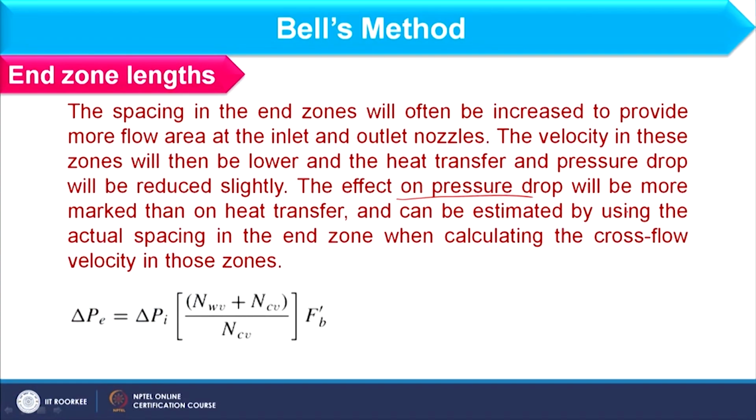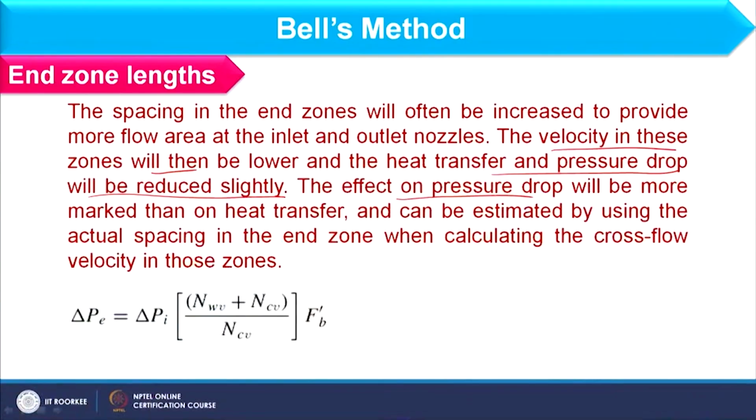The velocity in these zones will be lower, so heat transfer and pressure drop will be reduced slightly. When I consider more spacing in the end zone, I have lesser velocity, which gives a lesser heat transfer coefficient and lesser pressure drop, and the effect of that we can observe more in pressure drop than in heat transfer.